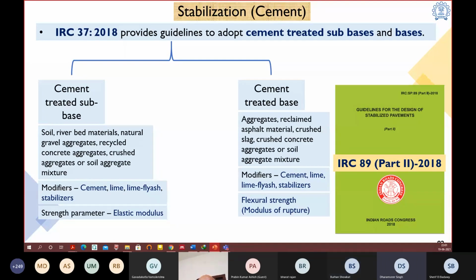This stabilization is another technique which is having a lot of interest in India as of now. Right. In fact, if you go further down, maybe the subgrade stabilization, which has a lot of benefits, so your subgrade foundation is very strong. And then we have the aggregate layers we are also stabilizing. In fact, we are also doing full depth reclamation. There also we do cement-treated base or sub-base, and on top of that we have different kinds of pavement design that we can consider.